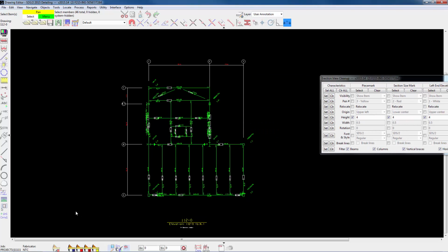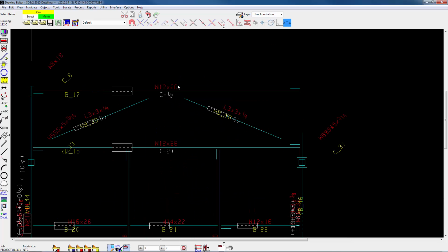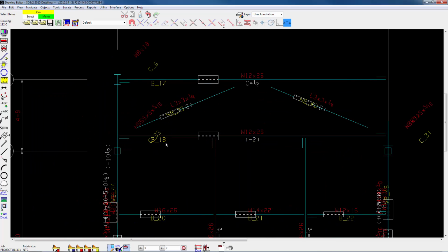Put a box around the building or your plan, menu button, okay. And all them changes have taken place. Menu, cancel out, and escape. So now all your text, piece marks, exercises are uniform height.